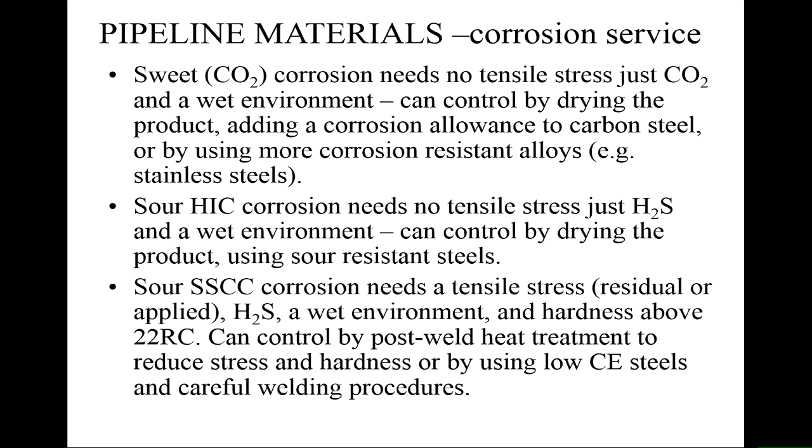So the region around the weld automatically has tensile stress because the pipes themselves don't move and the metal is fixed. If the pipes are allowed to move closer together, that can be reduced, but you can never get it down to zero. So that tends to mean that the weld region is the most susceptible to this stress corrosion cracking mechanism.